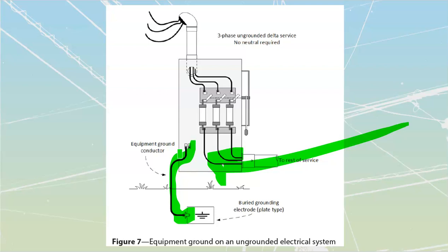In the Fraser Valley here, in a lot of agricultural buildings, you need to run a bond inside of that. You'll find the rules for that additional bonding inside of section 22, which is where we deal with wet and corrosive locations. You'll also find the rest of them inside of section 12. Section 14 talks about areas where we have to bond down EMTs.